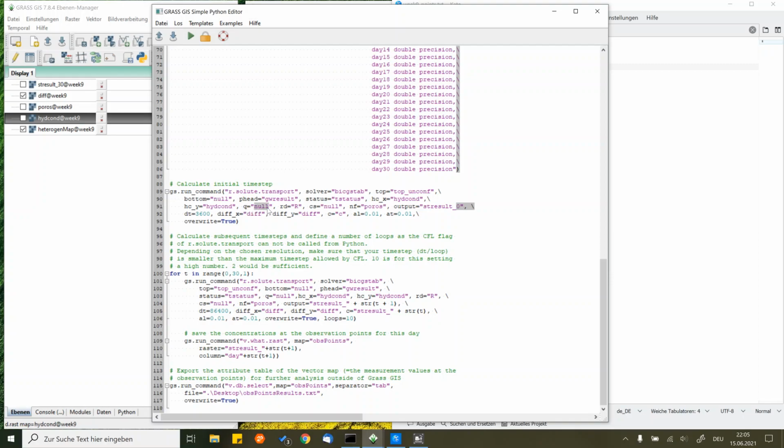But as you see, I can simply set it to 0, so we don't change the physics. It's just, as I said, a bug in the computer code. Otherwise, if you do not provide the water source, it will run into a problem. So we do this simply to have an initial distribution, and then we can subsequently calculate the following 30 days.